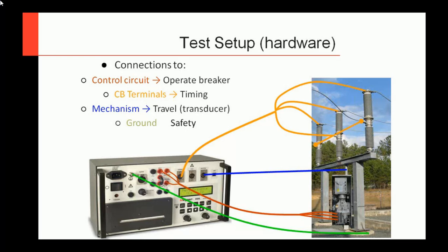No. The pre-insertion resistors come in and close, and then the main contacts come in. After the main contacts come in, even though they're technically shorting out that resistor, the resistor will still come back out of contact. So only the main contact is actually engaged when that circuit breaker is closed. And this does add a little bit of complication to the internal designs of that interrupter.